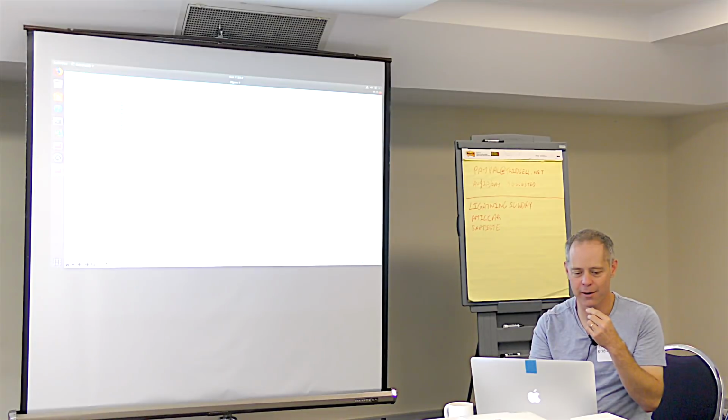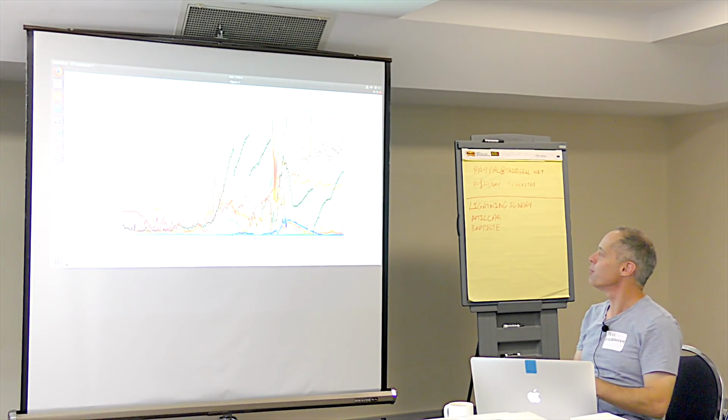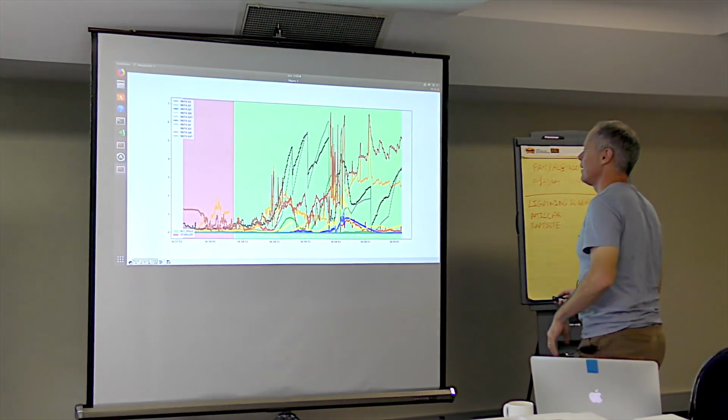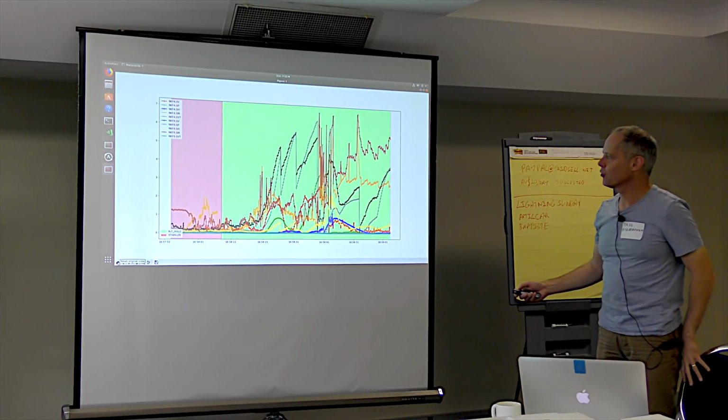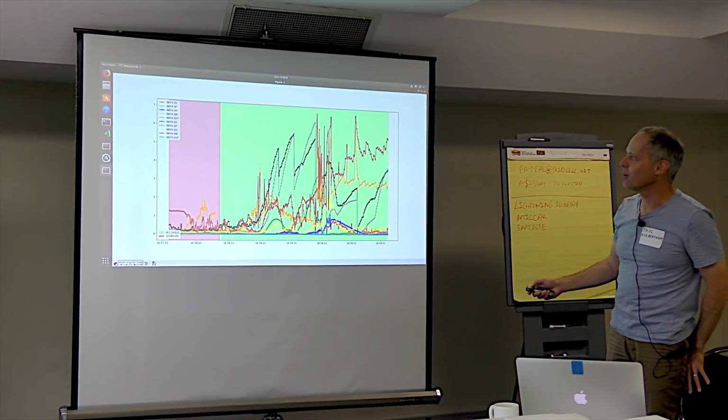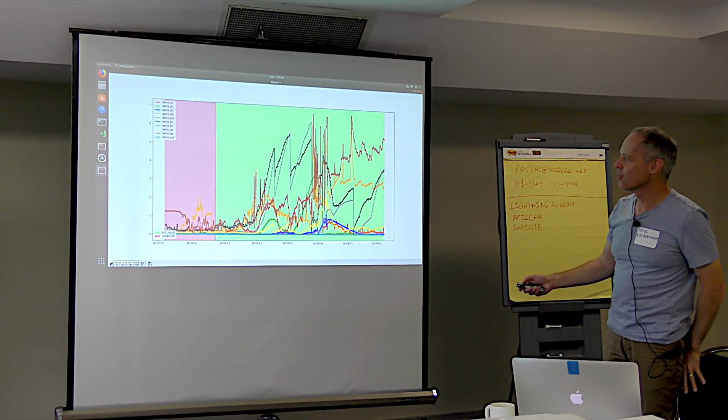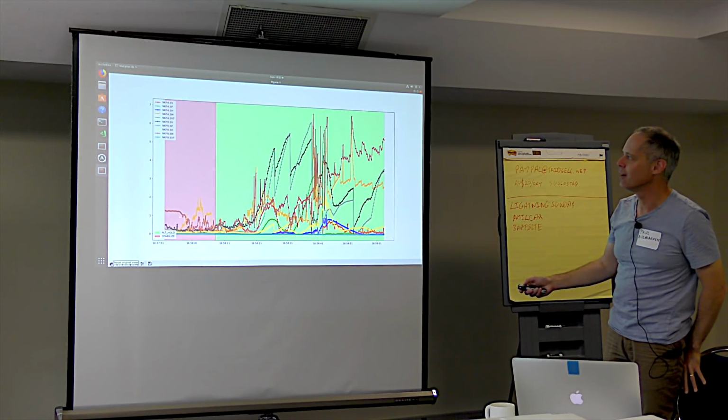Now this was a very unhappy flight computer. There's a lot going on here. Well, straight away, before it stabilises, you can see that we've got the magnetometer innovations. It's failing on the magnetometer. The magnetometer on IMU 2 was failed right from the start.